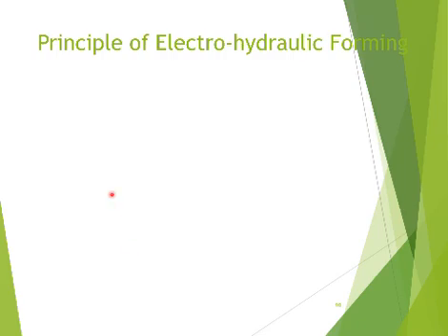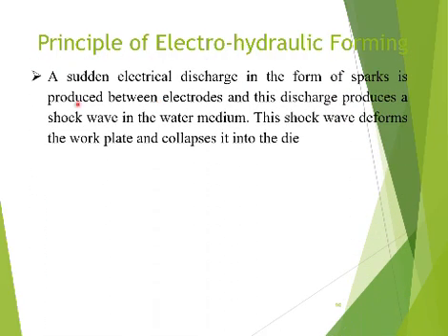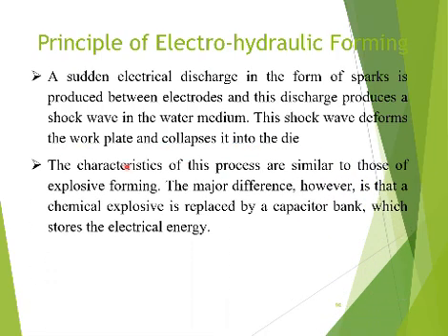In this slide, we discuss the principle of electro-hydraulic forming. A sudden electrical discharge in the form of a spark is produced between the electrodes, and this discharge produces a shock wave in the water medium. This shock wave deforms the work plate and collapses it into the die.